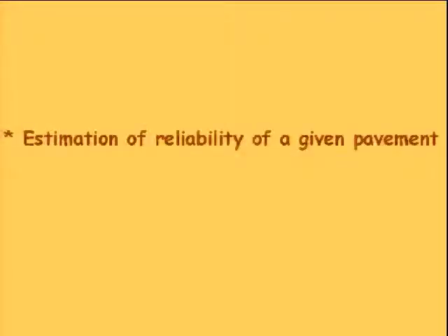Now I have two questions. The first is the estimation of the reliability of a given pavement, which is easy because you can consider the variability of all the parameters and finally simulate. Of course, it amounts to a large number of simulation runs, and typically it is done by the Monte Carlo simulation technique. That's because we cannot analytically find the reliability of a typical pavement. That's because of the difficulty in the analysis: we cannot find how the distribution is going to look when the distributions of the other input parameters are known.